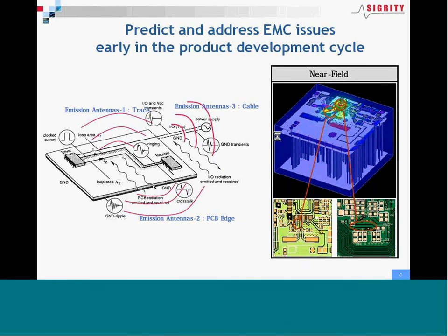What we don't consider in Sigrity tools, but we would suggest more a 3D EM simulation approach, is emissions from a cable or possibly emissions from a heat sink. But as you'll see later, you can do a lot with your board for design side consideration and reduce tens of dB the emissions from your boards just from considering the microstrip traces and the power ground emissions. Next slide.